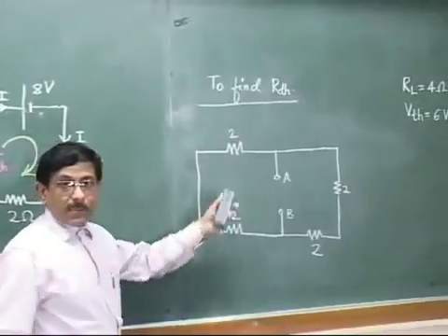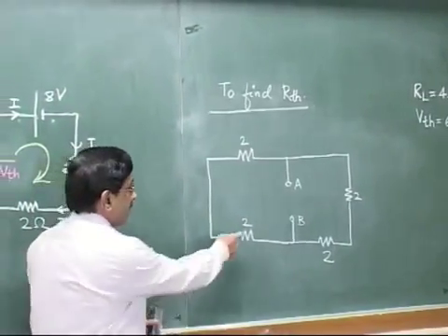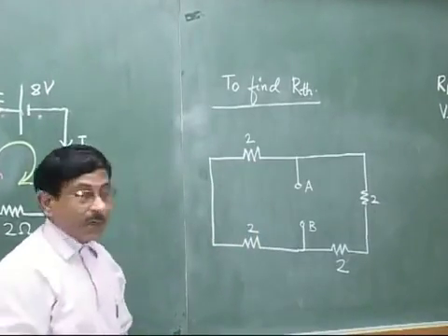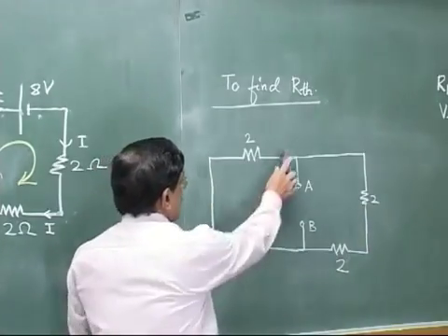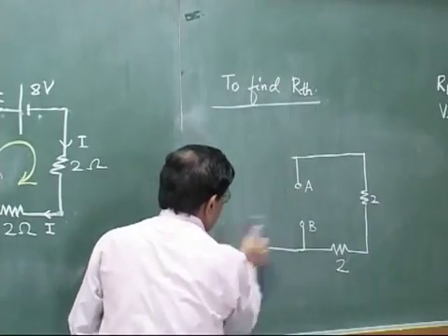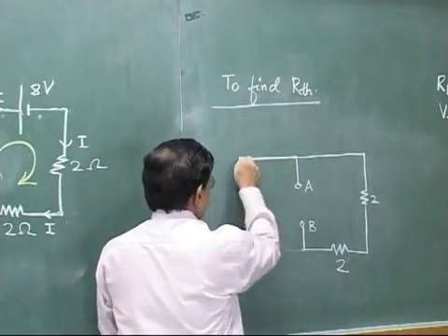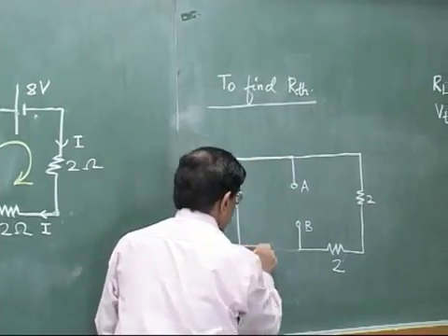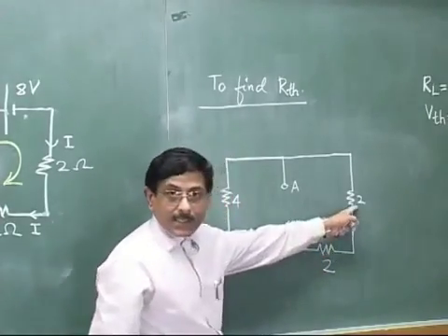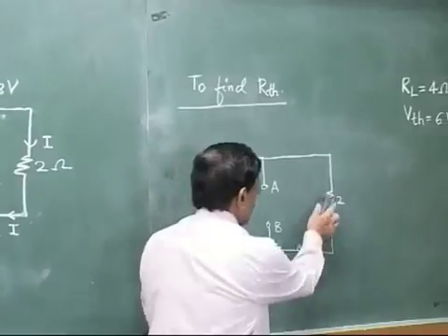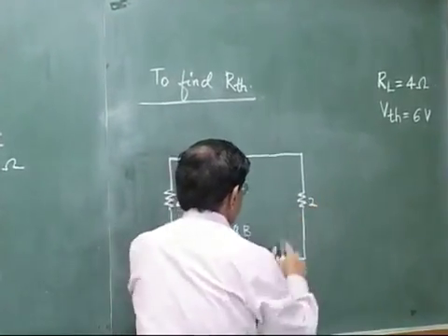And now see, it is very simple here to find out the net equivalent resistance across points A and B. These 2 and 2 will be a 4 ohm resistor, and also these 2 and 2 in series 4 ohm resistor. So your next step will be, instead of these two resistances, I will show just one single branch of 4 ohm. And for this 2 and 2 in series, I will show the sum 2 and 2 4. So the circuit will be reduced to this.